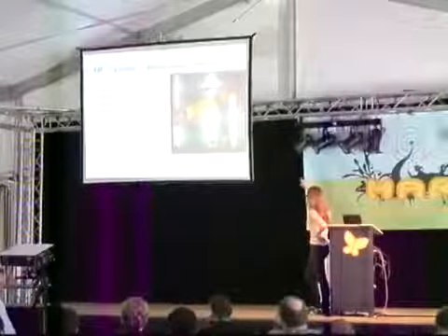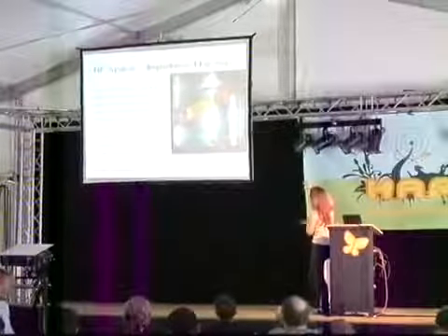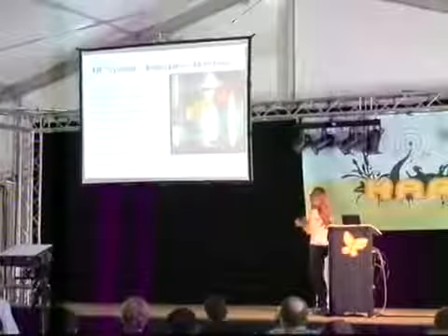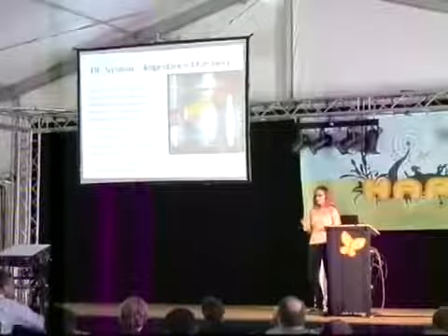You take your hacked-together pseudo-inductor coil, put it in parallel with a capacitor of a known value, and figure out the resonant frequency. Since you know the value of the capacitor, now you know the value of your inductor. Then you put that inductor in parallel with the copper D-shaped vacuum system and check the resonant frequency. That tells you the capacitance of your vacuum system, a number you'll need later on.